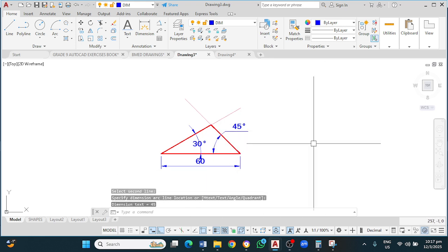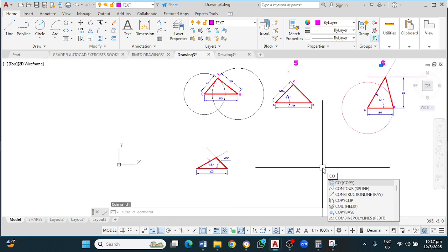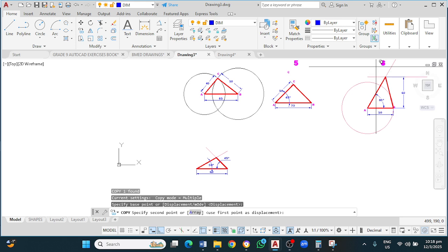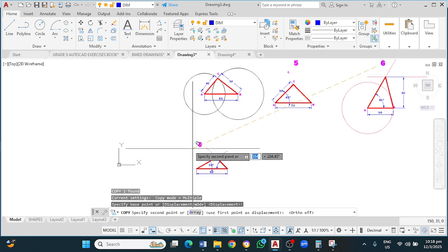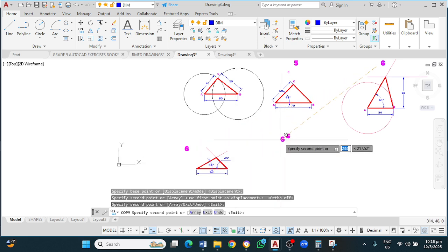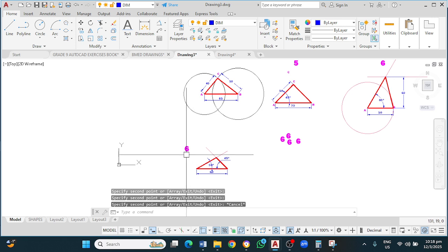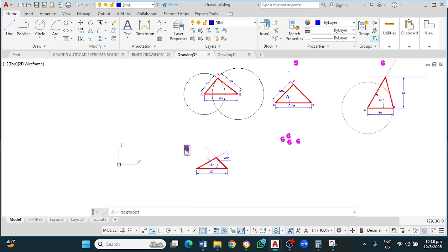So now question number 7 is done. I'm going to copy this. CO, enter. Turn off ortho. I'm making a number of copies of those for further use.